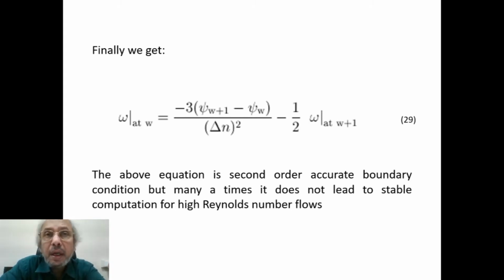Maybe a little higher order discretization is needed. So overall this is a solution strategy, and a strategy for increasing accuracy for high speed flows, upwinding. We have discussed everything, but obviously for a practical problem one has to try and see what works best.